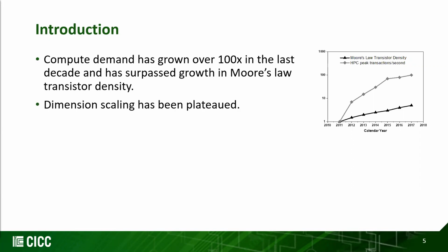The transistor dimensions laterally shrank from 10 micrometer in 1970s to around 22 nanometer in 2010. Short channel effects like interface scattering, DIBL, etc. made transistor operation in a desired way harder, which was then alleviated by FinFETs and other non-planar technologies. While we are at the brink of what lithographic process can achieve, and even what techniques like fin depopulation can provide, we can say that the dimension scaling has plateaued.